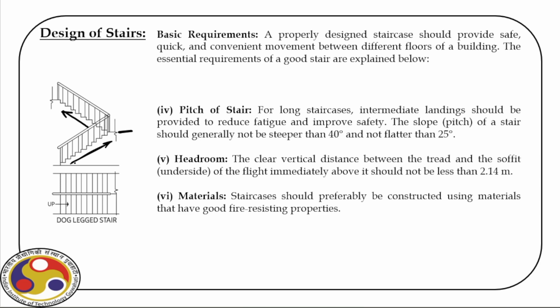When we design this, we should keep in mind that this angle is extremely important. It should not be steeper, it should not be flatter. So, we normally design stairs between 25 to 40 degrees, right? That provides a very comfortable movement from one level to another level.